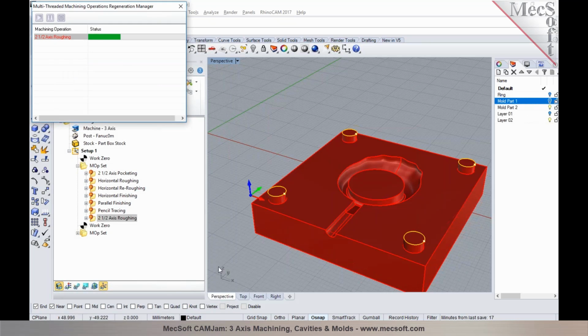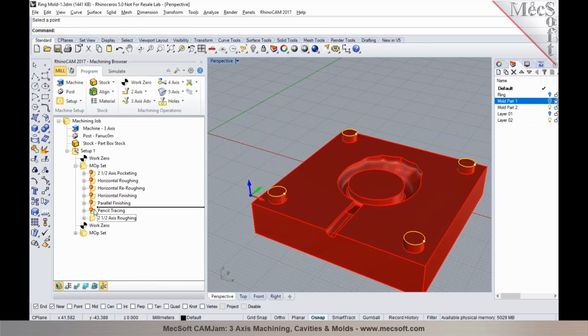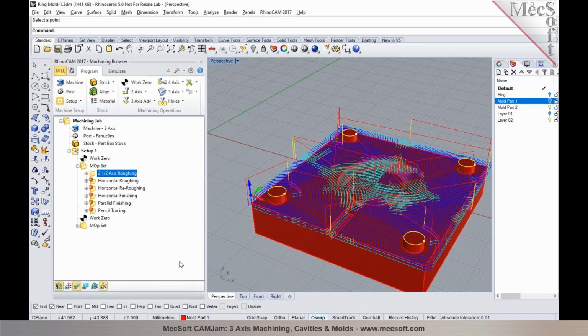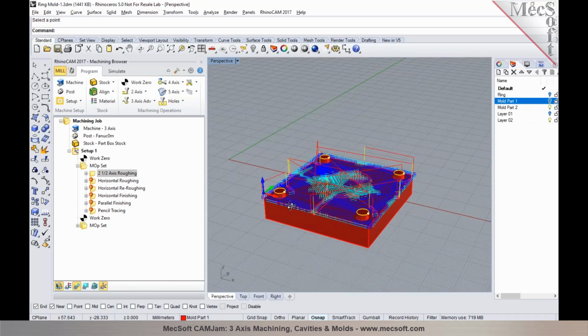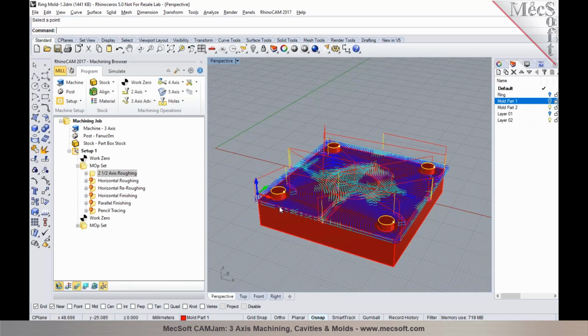And just a note on the roughing operation, it's a little bit different from the facing and the pocketing operations in the sense we use the stock model to figure out the extents of the cut. So we automatically figure out the extents and then use any containment regions to stay off of, as you can see here. Thanks, Uday.